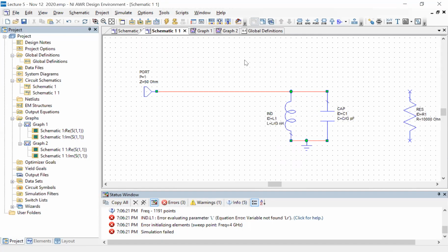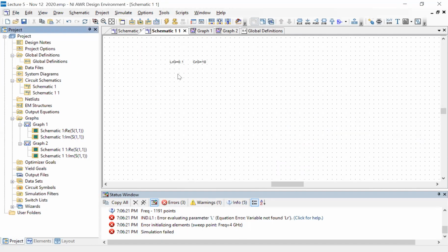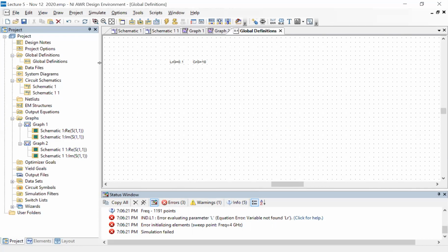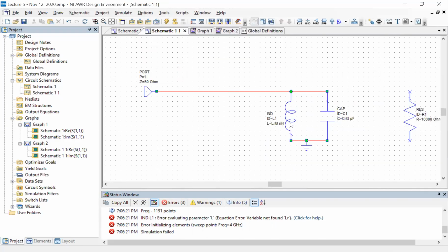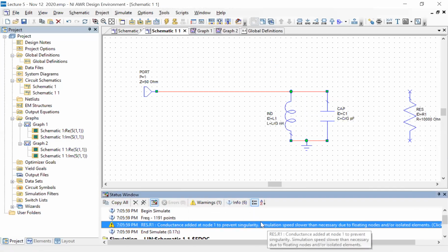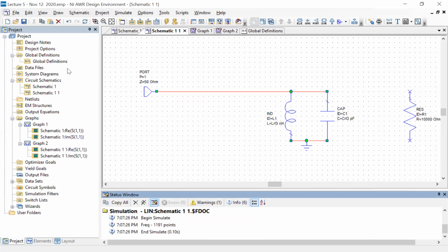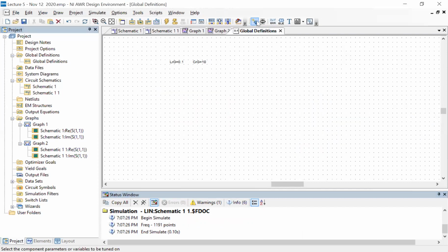And remember that everything you define here has no units. These are dimensionless numbers. All the units are defined by what is set after that. Okay, it's just purely numbers. So now if I try to run this, then it's fine. Okay, so it runs. So that way, again, you can go to global definitions, put tuners on them, and if you tune them, it will reflect across all of them. Okay, so three things: subcircuits, local variables, and global variables, which have to go in a separate location.